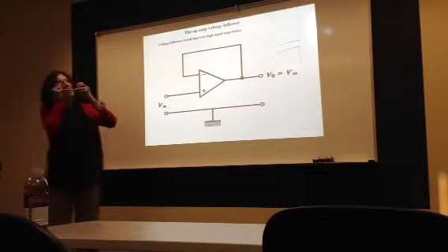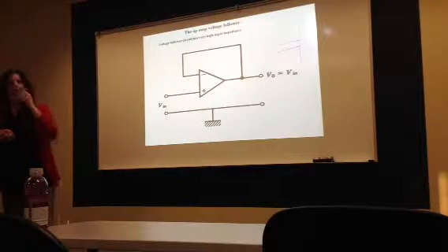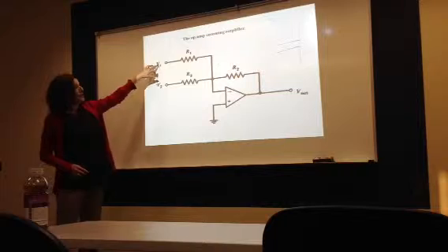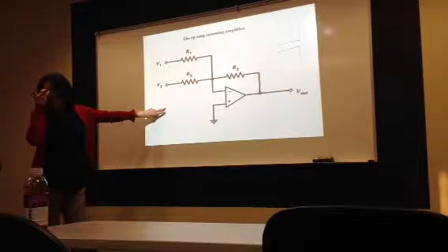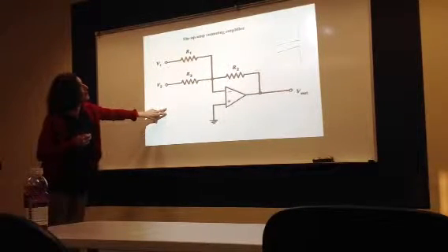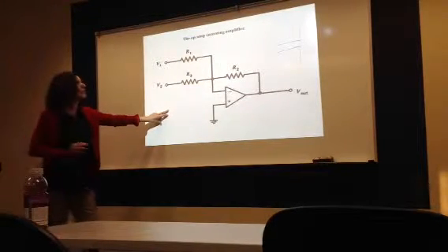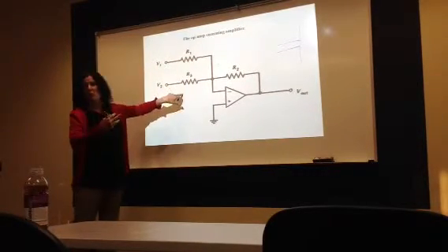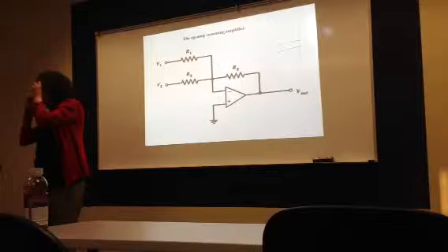Then we started with the op-amp as a voltage follower, and we said it has very high input impedance. We were able to isolate, and we started to design the signal conditioning. You remember where we used that? Anyone? In one of the labs. Yeah, we used the op-amp as a summing amplifier to do what? Digital to analog. Very good. Digital to analog converter, and we used weighted values of the resistors, 1/8, 1/4, 1/2, and so on, right? And that's how we use that one.